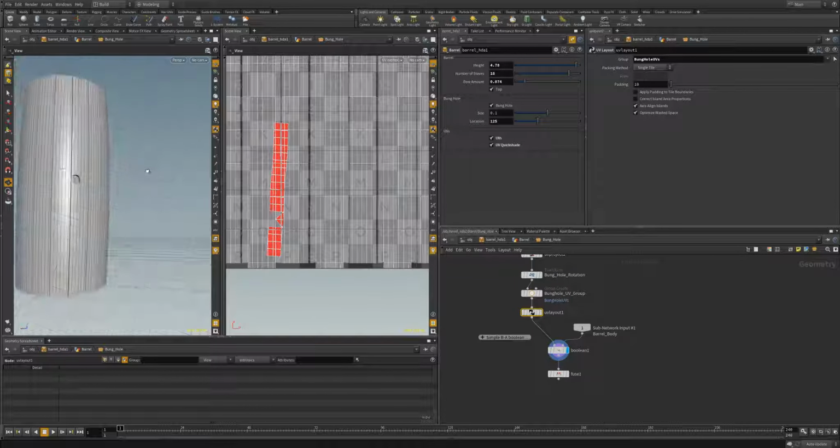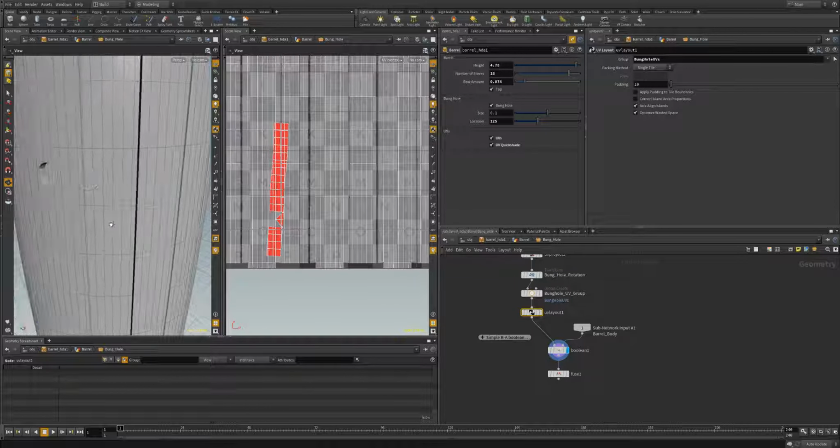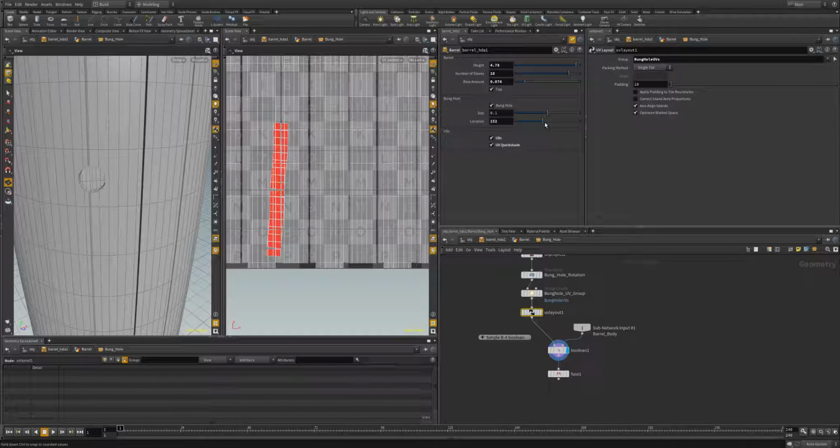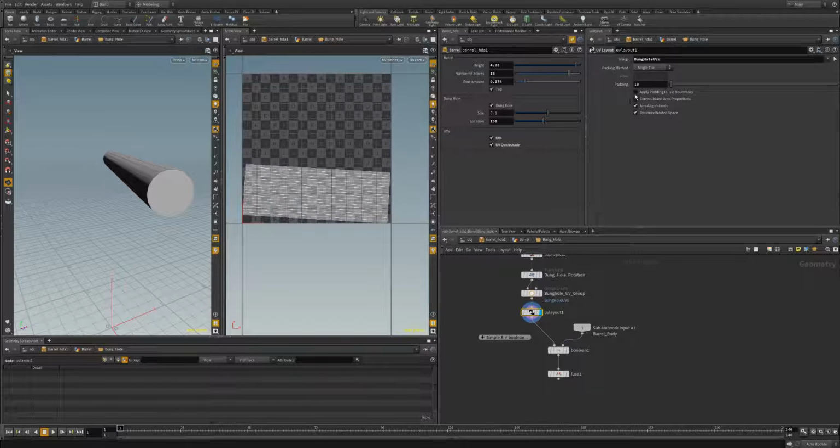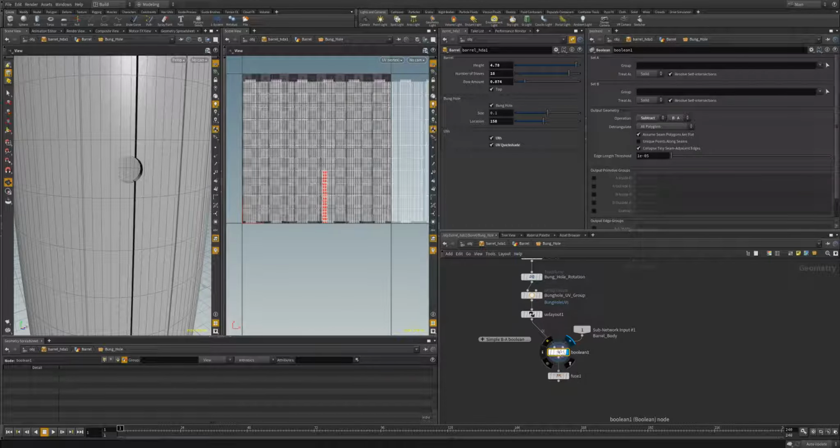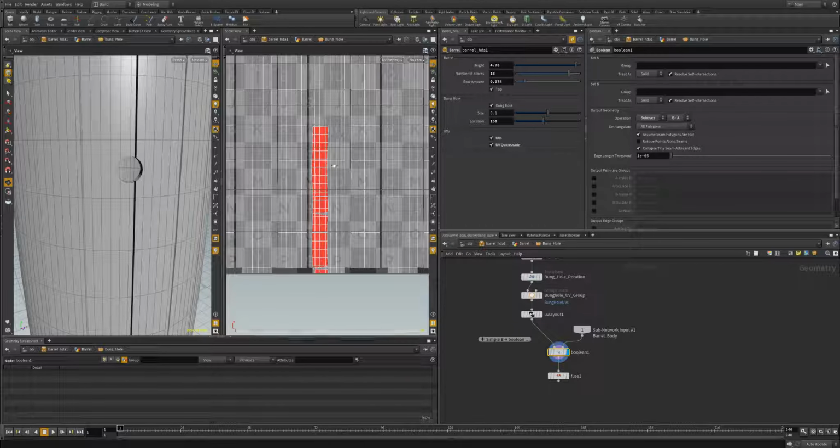And then when we check out our operations here, it looks like we'll still get pretty good UVs, and it's even handling the cutout here for when we break over into the seams of our staves. Let's go and correct island proportions. We'll turn off axis align because it was actually messing up for us, and that's looking pretty good. We'll just step back down to our fuse.